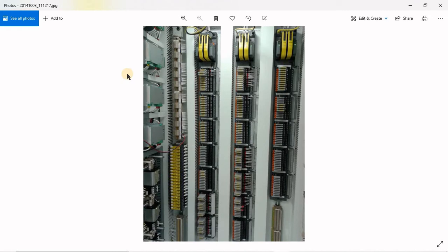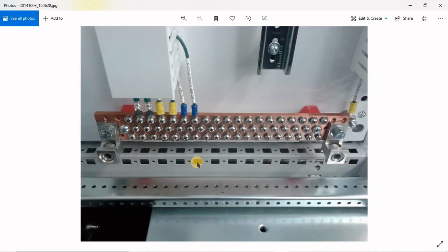Let's look at some pictures. Maybe we will explain. In this cabinet, this is an SIS cabinet, you find all the power distribution on the left, and then your SIS system in the middle, and we have maybe the communication on the right or something like that. So one good thing about it is that you have all your 120 supply on one side. And on this side is, let's say, the I/O and your controller and things. So this is one way of doing it.